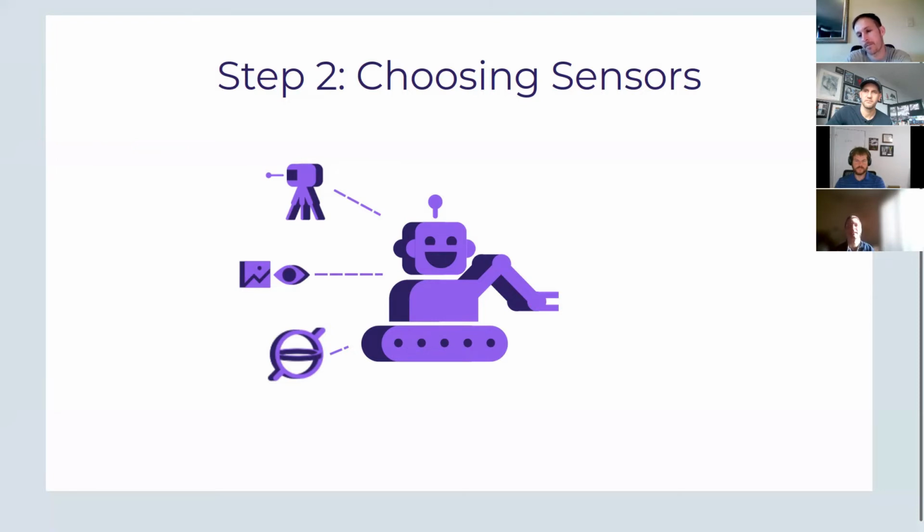It's 80% of the performance at 20% of the cost. If you want a gyroscope that's got really high performance, it just gets so expensive. So you kind of want to mix it with a camera or a LiDAR. I definitely think that mixing 2 or 3 sensor types together will do more robust and better localization and mapping. But you have to deal with the software. You have to process it somehow.